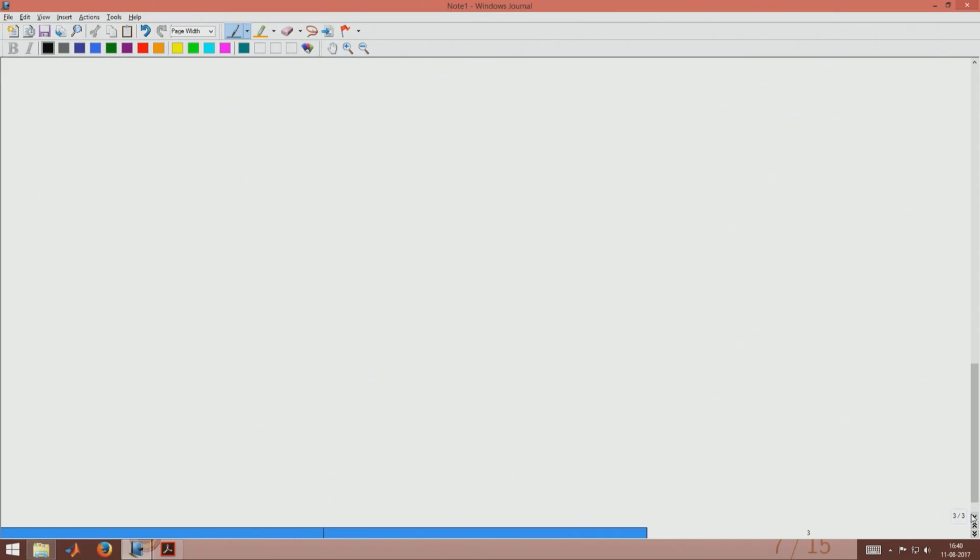So, what we can do next is look at how these stress components are specifically when we have a cone and plate kind of device, which we will see later on is used for measuring the viscosity of the fluid. So, cone and plate, as we will see later on, is a device in which we have a cone which is rotated at a given controlled speed. It could also be oscillated, and then we have a plate.